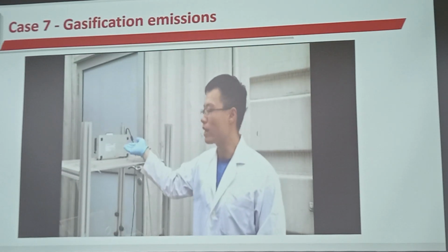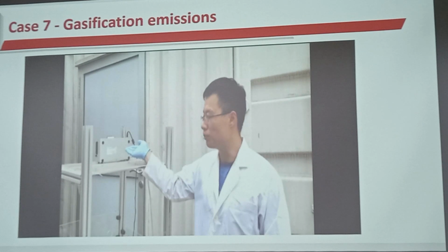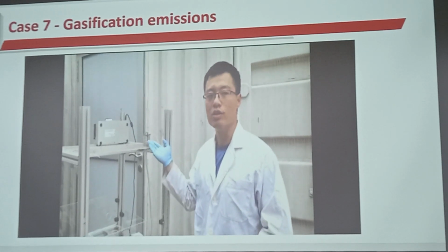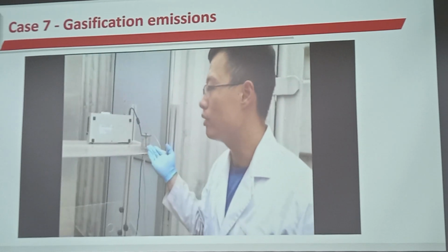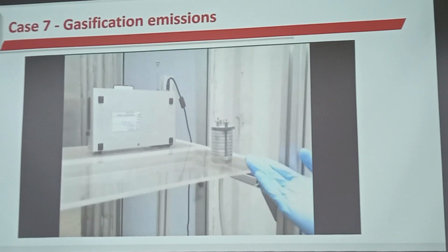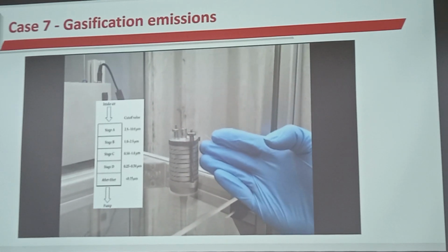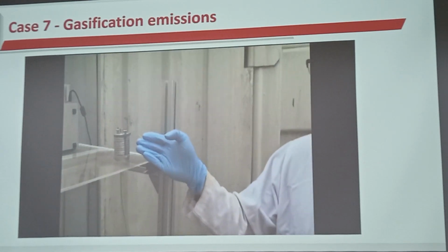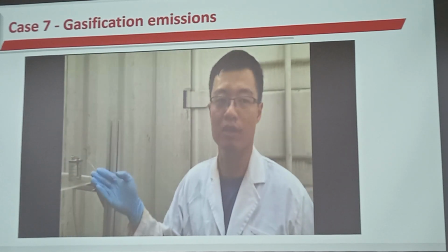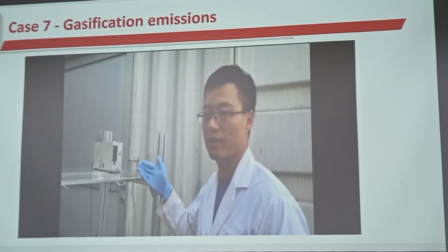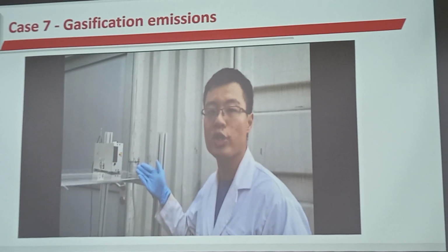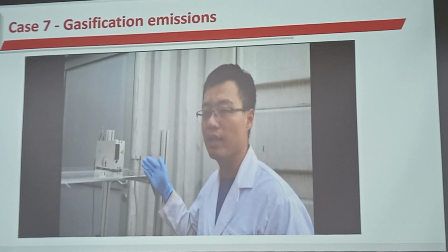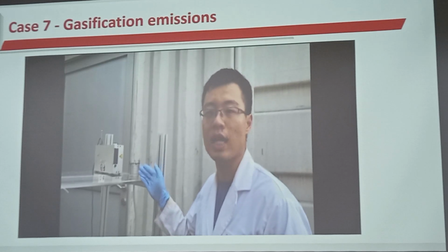We also have another spectrometer for outdoor measurement that was placed outside the container. This is a cascade impactor. It is used to measure the size-dependent particle mass concentration. It has 5 stages. Particles with different sizes will be captured onto the different stages. Before and after the field measurement, the filters will be placed in a constant temperature and humidity chamber for 48 hours, followed by gravimetric analysis. After that, we will perform chemical analysis on these captured particles.